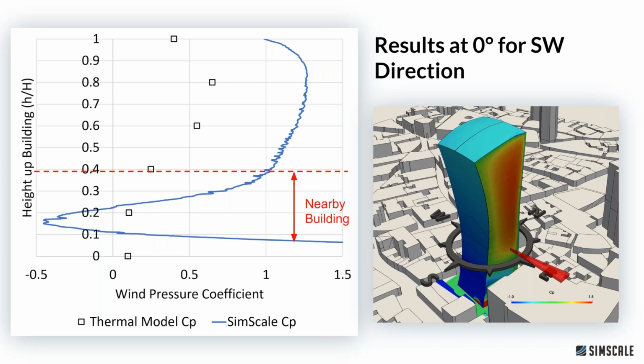Okay, the same building, the same angle of attack on the same facade with the context now taken into account, with the turbulence taken into account, etc., etc. Okay, and you can see on the y-axis, this is the height of the building. This is a ratio of height of the building. Okay, so the small h is the point on the building where we're taking a reading. So imagine that's, let's say, an opening height, let's say window.